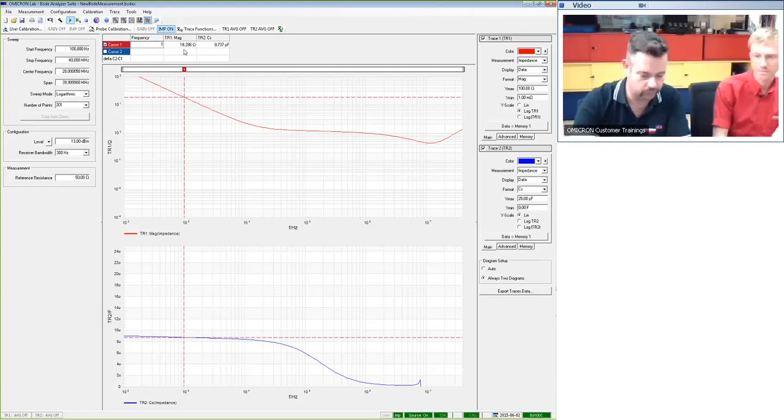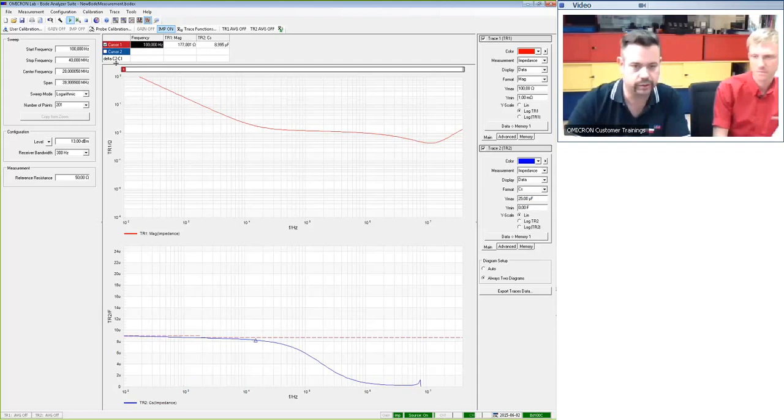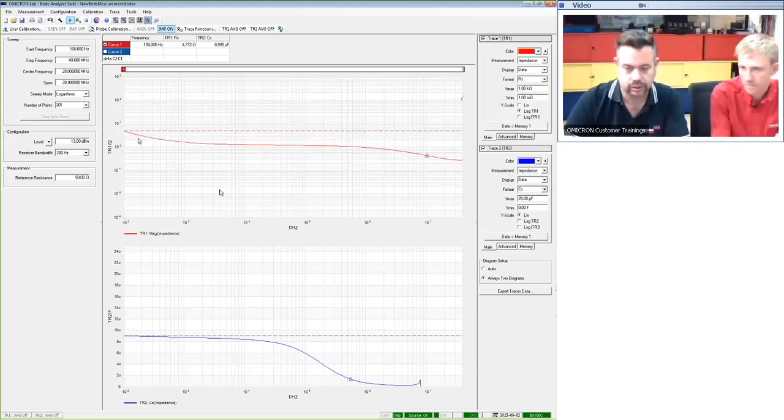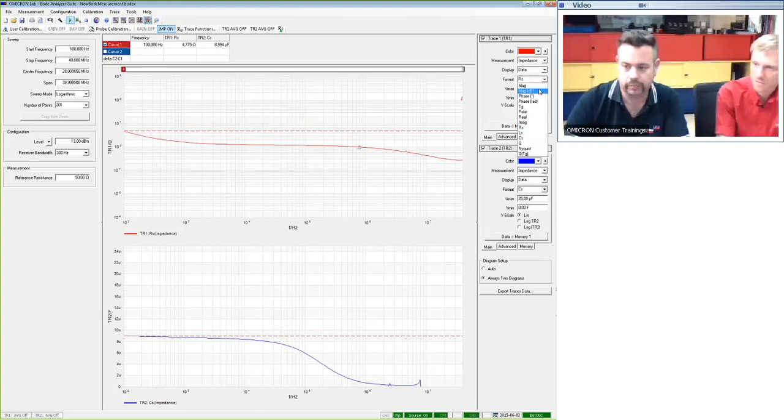If you look at 100, it's bigger. It's 8.9 microfarads. This capacitor has plus minus 20%, so this is definitely within the range. Now what we can do is also have a look at the ESR. And this is the ESR, and let's store this data to memory. And let's use a different capacitor, but before we do so, we will go back to magnitudes.